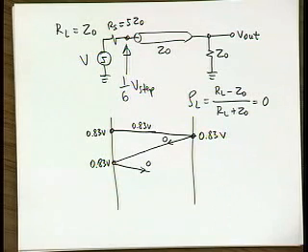And so this was all analysis for the lossless transmission line, when we assumed that the resistive effects were negligible. That is a fair assumption in most cases for PCB level analysis. Now for the on-chip analysis for high frequency signaling, we often have to take resistive effects into account. What we are going to end up with is a lossy transmission line, where on top of the reflections, we also have attenuation along the way. So we have a combination of what we just analyzed in today's class and, in the previous class, the diffusion.